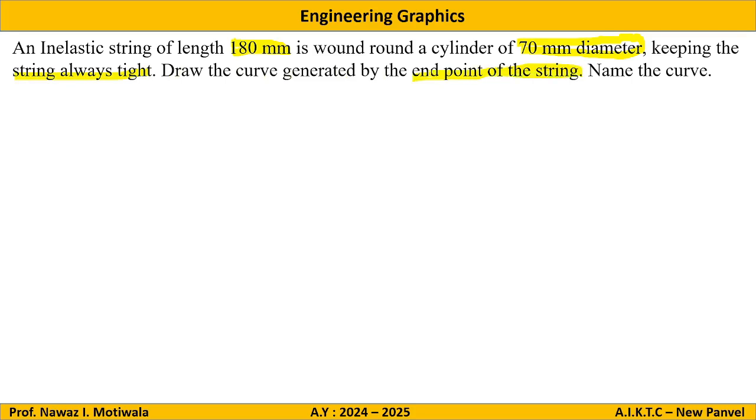So this sentence, draw the curve generated by the end point of the string, gives us the hint that we need to draw the involute. So here it is, name the curve. So after drawing, we will name the curve as involute.